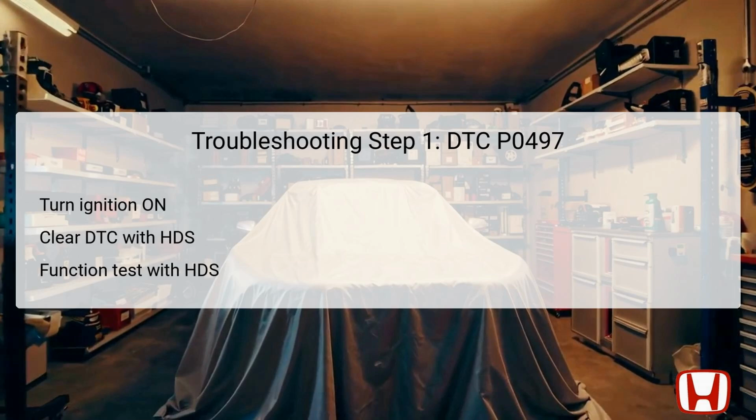The first step in troubleshooting DTC P0497 involves verifying the problem through initial checks. Begin by turning the ignition switch to the on position, I, ensuring that all vehicle systems are activated without starting the engine. Next, use the Honda Diagnostic System, HDS, to clear the DTC from the system. Clearing the code allows for fresh data collection as you proceed.